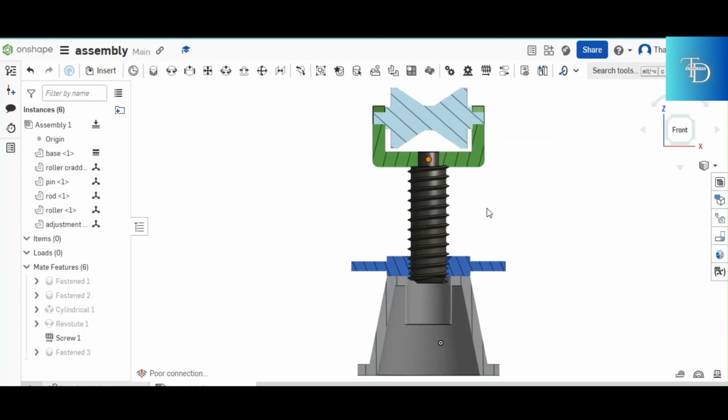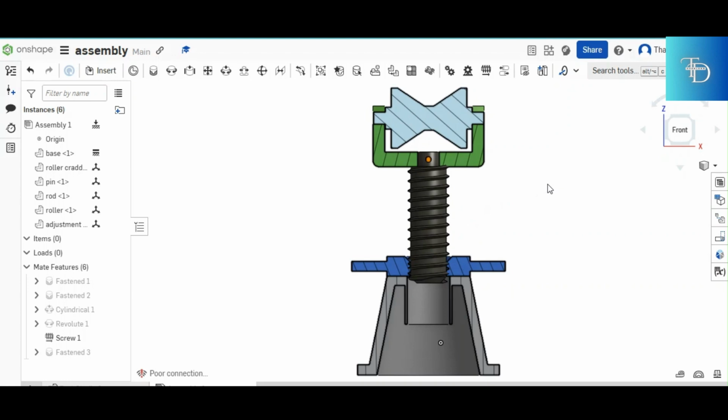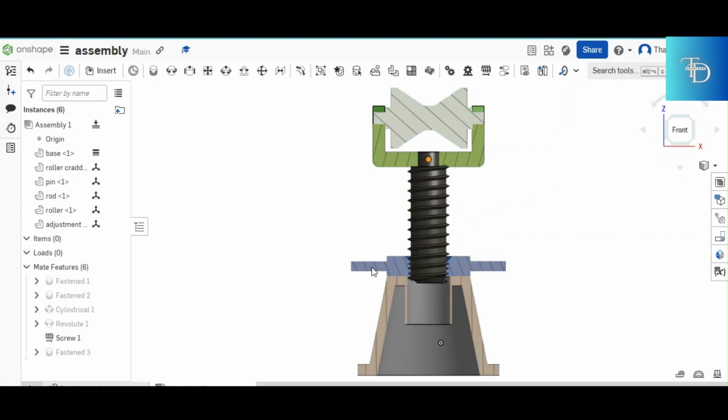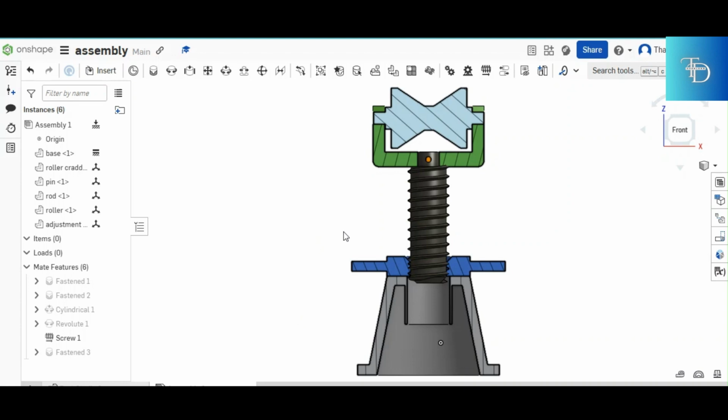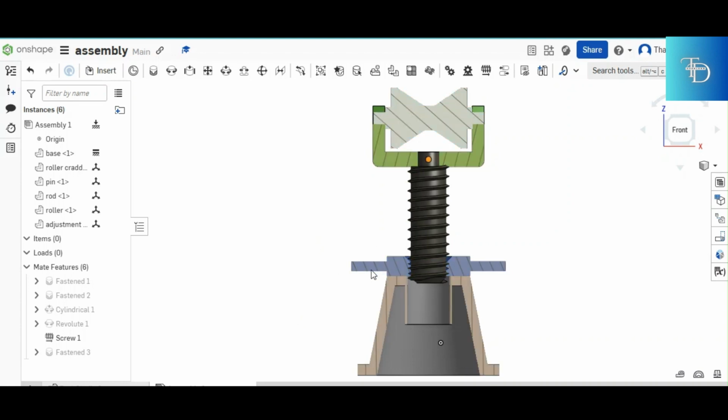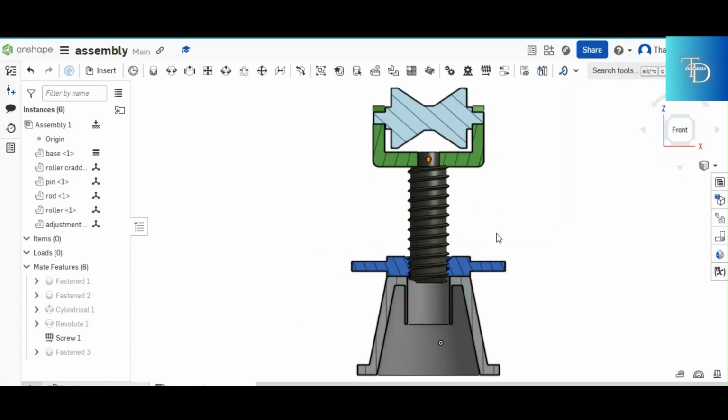So my point is, if you are sectioning those parts, the point where there are two different parts coming in contact, that is where your sectioning lines start changing directions. So part number one is different from part number two. Those are two different parts. So they meet where, at that line. So exactly at that line, your sectioning lines should change direction, exactly as it happened right here. And then same thing applies on this top side right there.